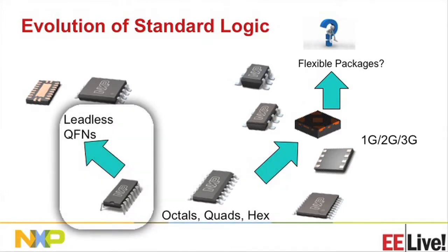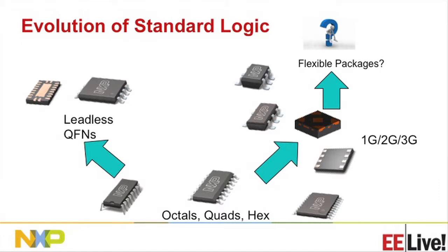Another trend is to keep the bigger pin count packages and more functions still on a single package, but move into QFNs. This is again the leadless packages with a bigger pitch and thinner in terms of height.